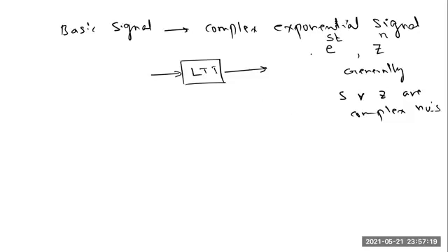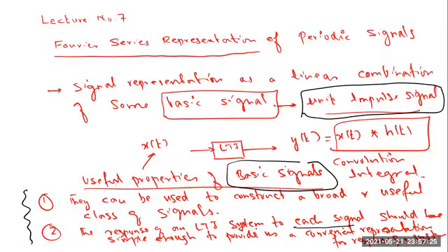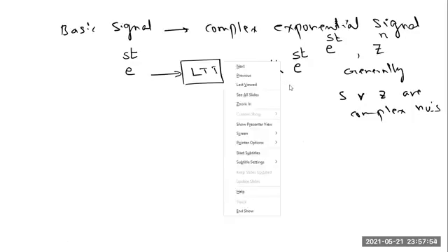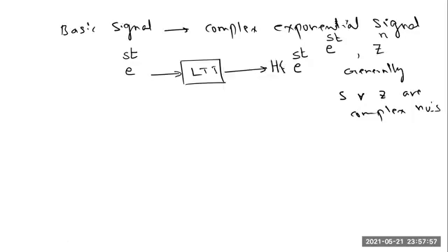So let's find out whether this signal has this property. Which property? The second one, the response of LTI system to each signal should be simple enough. And we can easily see this, and I will prove this in a short while, that if this is a continuous time system, and if you apply a signal of the form e raised to power st, the output of the system to this input is simple enough. It will be the same e raised to power st multiplied with some constant that I represent as h function of s.